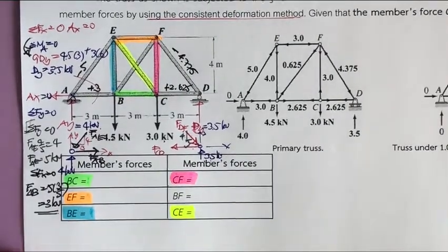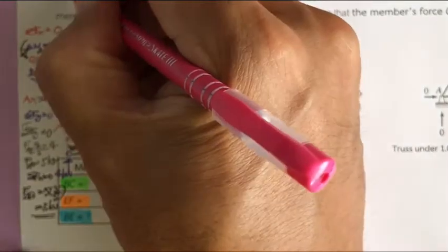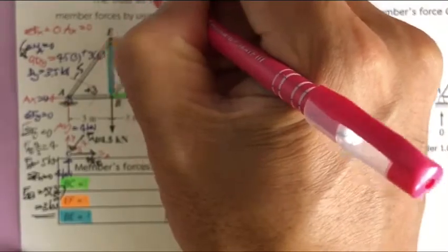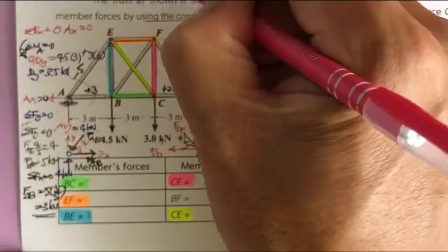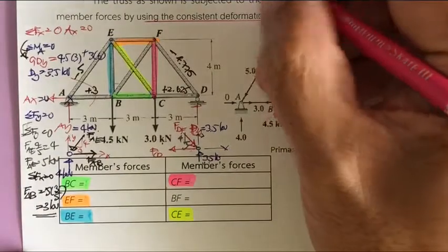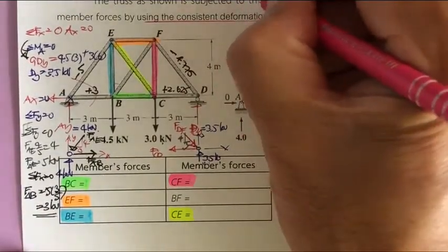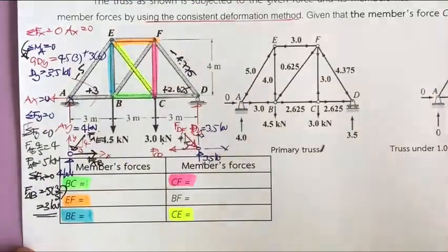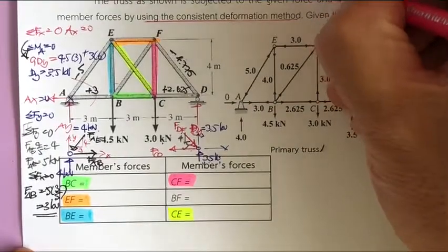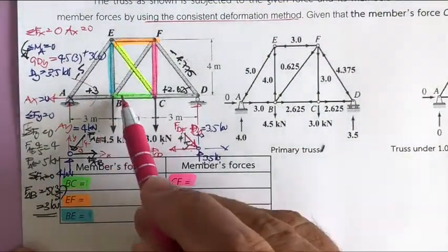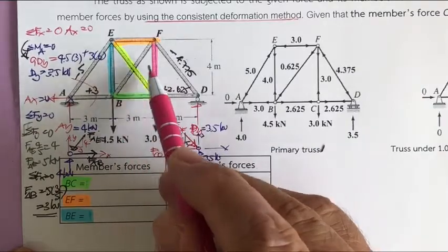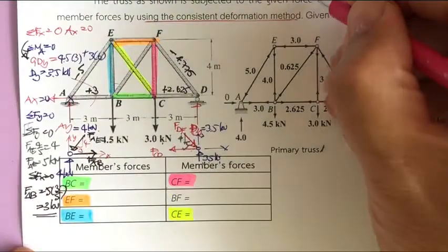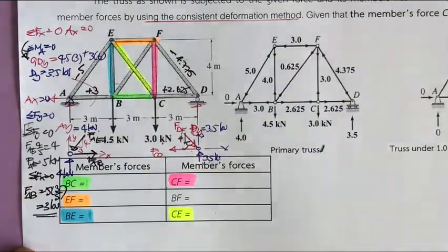And how do you check this structure is going to be a statically indeterminate truss, and it says internally. Internally is due to what I just explained to you. You check with what? B plus R. Okay. How many B? 1, 2, 3, 4, 5, 6, 7, 8, 9, 10. B is 10. Plus R, you have A sub X, A sub Y, D sub Y. 3. So this is going to be 13.